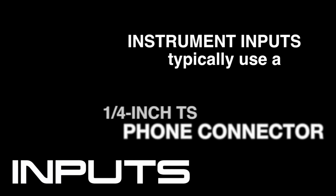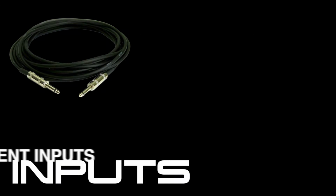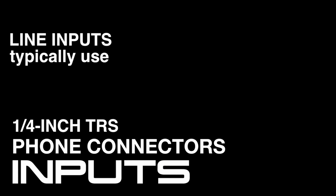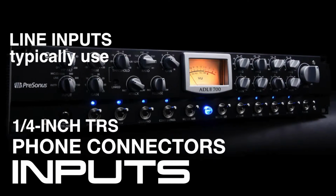Instrument inputs typically use a 1/4-inch TS phone connector and are best suited to the signal that comes from an electric or bass guitar. These instruments provide a signal that's stronger than a mic-level signal, but still can require a little boost. Line inputs on most interfaces use 1/4-inch TRS phone connectors and are best suited and matched for use with outboard processors, mixers, and outboard mic preamps.